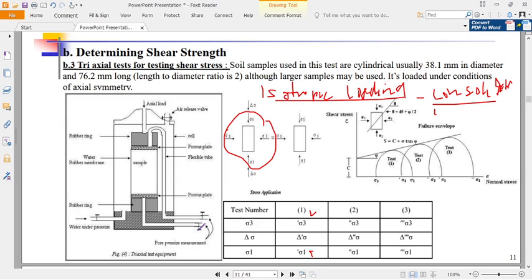So in these two cases, you can both measure deformation. The first case of consolidation, you put sensors to measure the lateral deformation and also the axial deformation. That is for unsaturated soils, is that okay? But if the soil is saturated and the drainage lines are open, therefore water is allowed to go out, then you measure the amount of water.